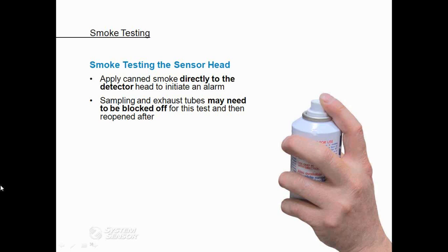So we recommend introducing smoke into the actual ductwork with canned smoke. This is an acceptable testing method and will ensure that not only your sensor head is functioning properly, but that you also have the proper airflow present.